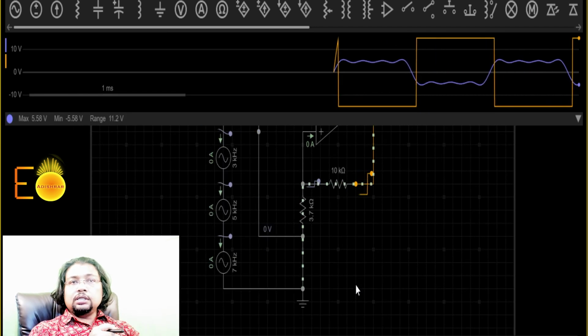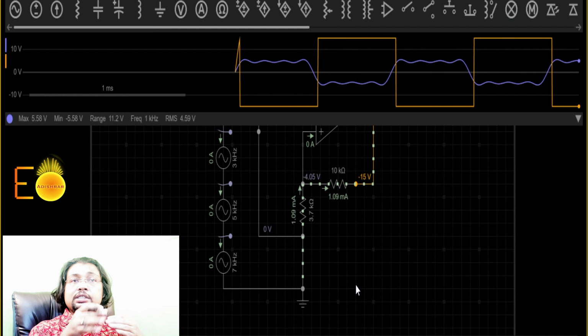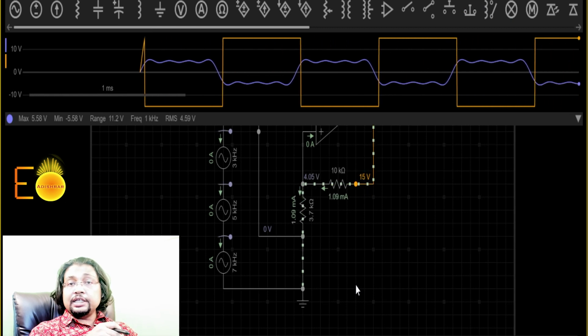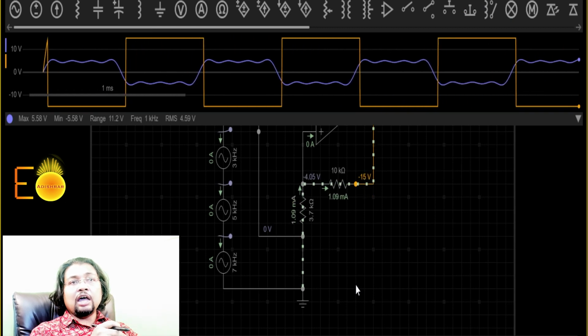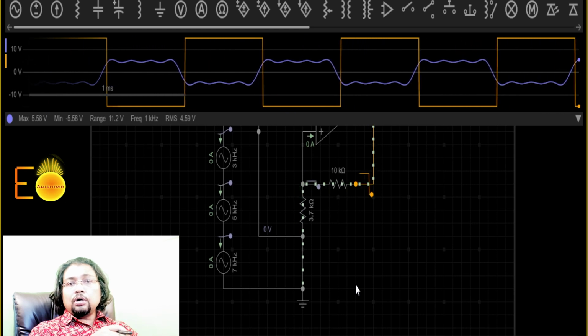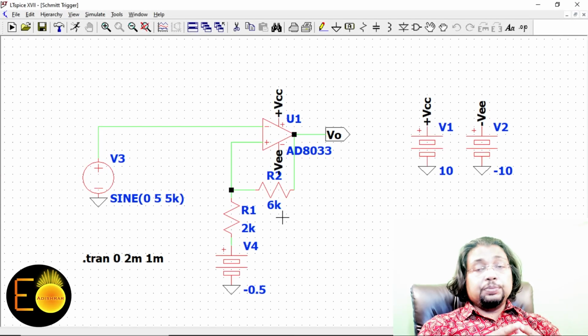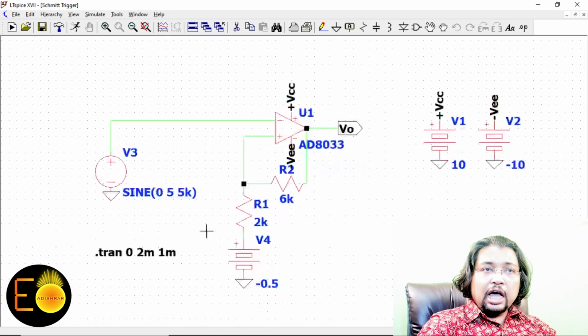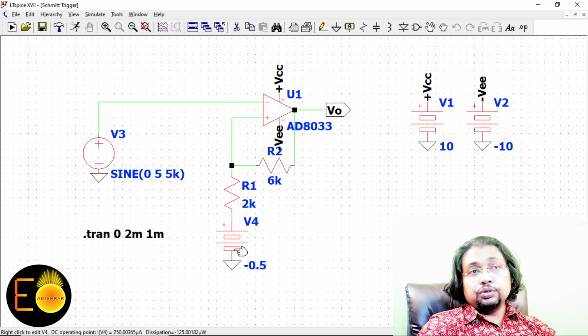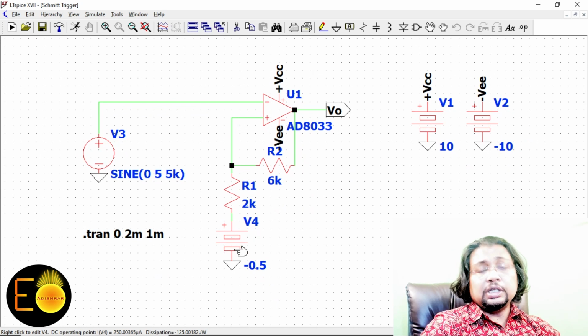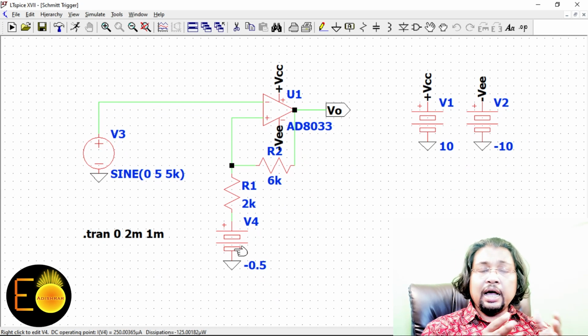So although the noise and bumpiness of the input signal exist, we still have a pure square wave. So here is the Schmitt trigger using an operational amplifier on the LTspice platform. As you can see here, I have connected an additional voltage source to provide a further reference voltage, and that is also possible using the Schmitt trigger, as I did for the ordinary comparator also.